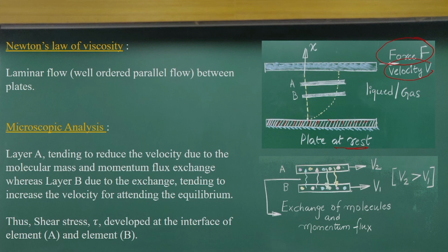As we know, whenever we have fluid flow conditions, we have the no slip condition. That means at these locations I will have velocity 0. At these locations, the contact of the fluid particles on the solid surface will give a velocity equal to the velocity of the plate. So, I have velocity v here and velocity 0 at these points. So, the no slip condition prevails at these 2 points as we are dragging the plate.